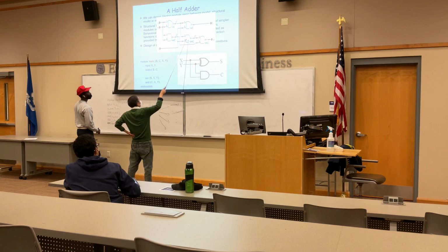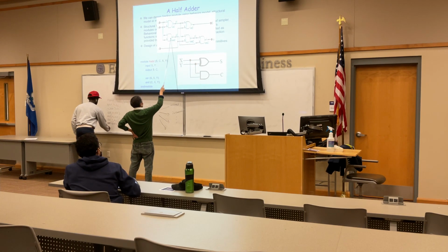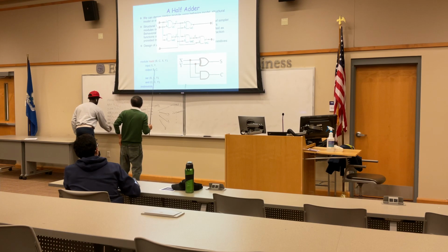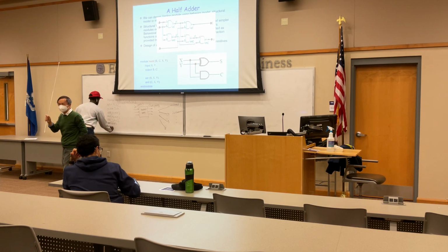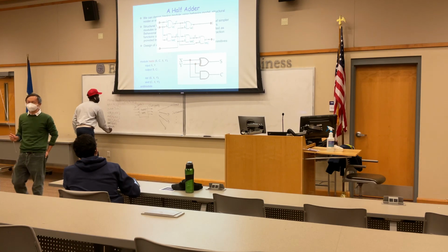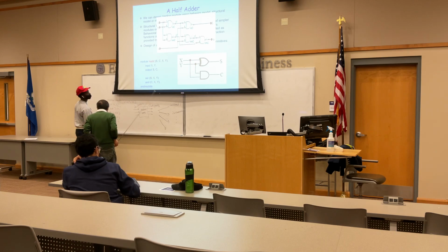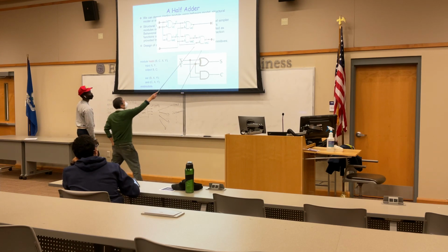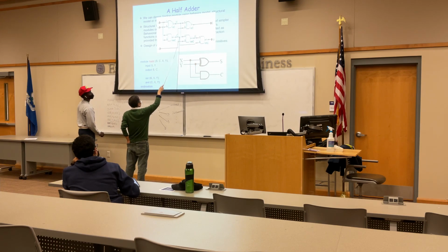And then we have another NAND with CO, N3, and N2. Yeah, let's do it together. Take out your pen and paper, and you can simulate this together. And then here, CO, N3, and C. Oh no, not C, N2.